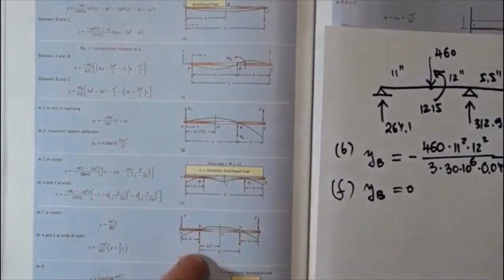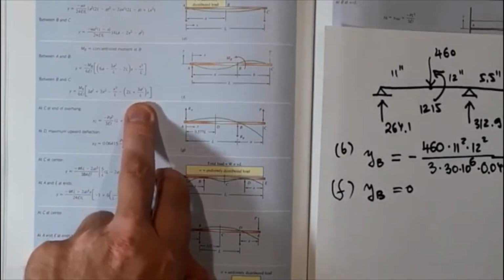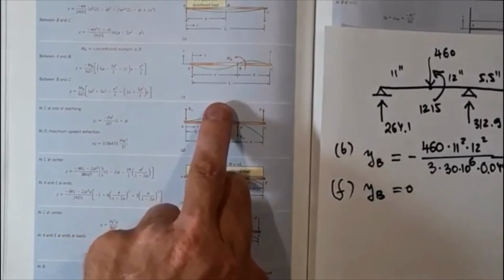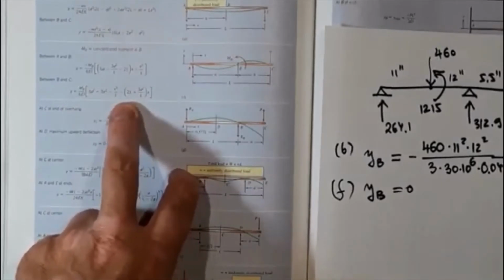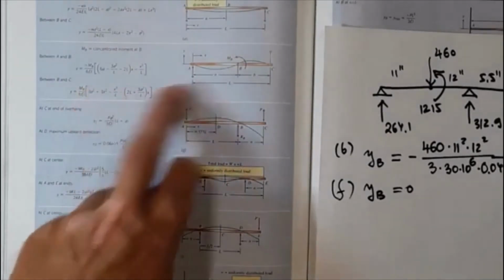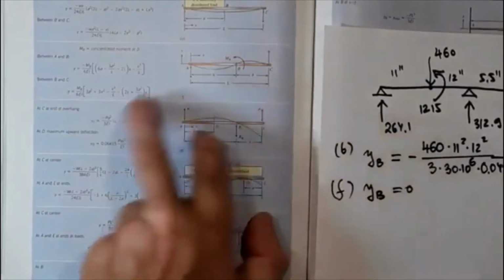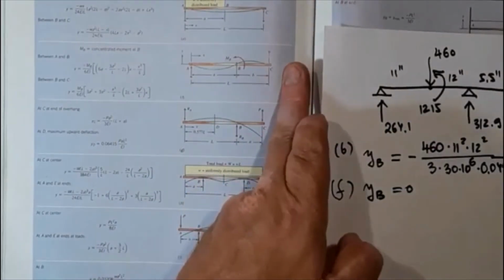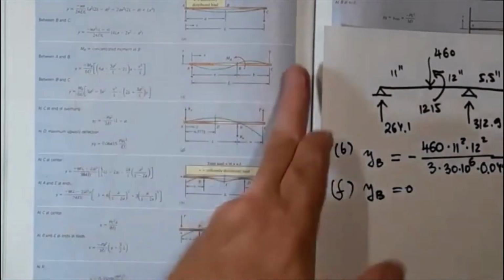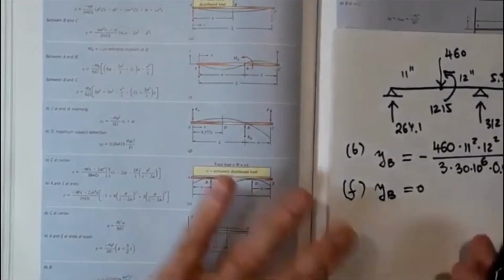we're going to have to expand this, apply this equation with an x value that is bigger than L to get deflection outside of C. It is x equals L plus our 5.5 inches offset. Okay, and then we have